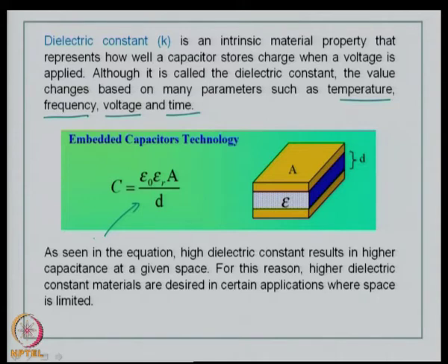If you want to, for example, use a sequential build up technology and employ different embedded capacitors in the build up, one above the core and one below the core, you can very judiciously use different capacitor materials to get different ranges of values, one at the top and one at the bottom, and these capacitors can be interconnected to the signal layers, the ground planes, and to the core by microvias. That is the advantage of using embedded technology.